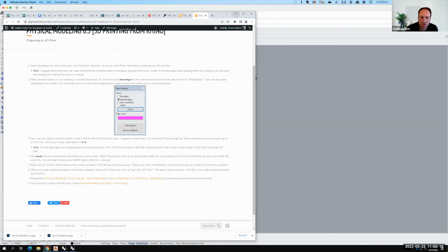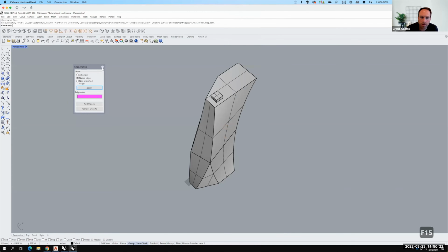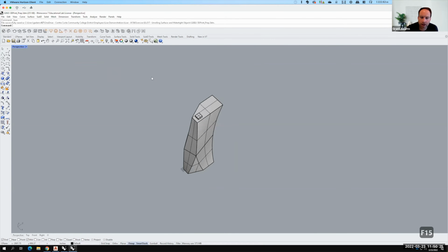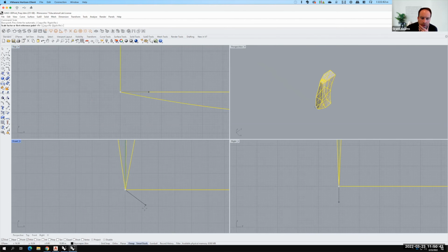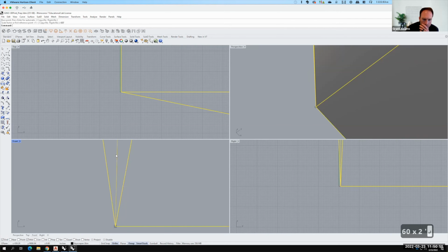What I'll do is scale this whole thing down so that the height is 4.5 inches. So let's select it, and I'm going to scale. This is a regular scale, not a scale 3D. We'll pick one of these bottom corners. Now it's hard because I can't really snap to the upper building because it's twisting so much. So I'm going to do this in the front view. I know what 600 feet is, so I'm going to turn on ortho, and I'm actually going to type in 600 feet to get an exact 600 feet.